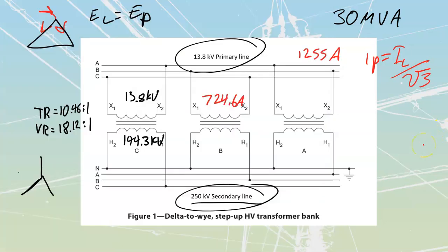This is going to be my line value of current, so we see that there's a very small amount of current that actually flows out over the line, 69.28 amps. And because we're connected in a Y, whatever current we feed out has to all go through the phase as well. So each of my phase currents is going to be 69.28 amperes as well.